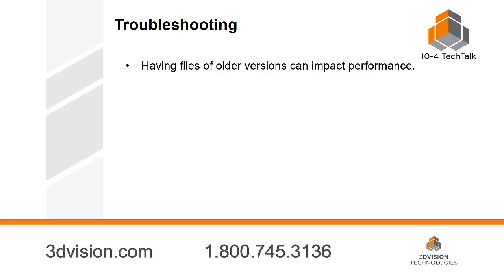So here are some troubleshooting tips that I have for you. The first thing, again, goes back to that version thing. What version of SOLIDWORKS do you have? Also, what version are your files at? A lot of people have legacy files that are still in 2014 or 13, and they're opening up these 2016 or 17 assembly files. That's loading all those old versions of components. When you do that, you go through a conversion process every time you open your assembly. So SOLIDWORKS is sitting there, converting all your components to the newest version. That can significantly slow down open time.